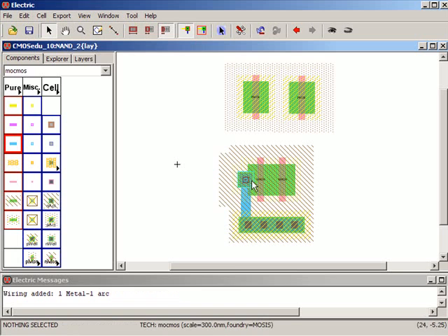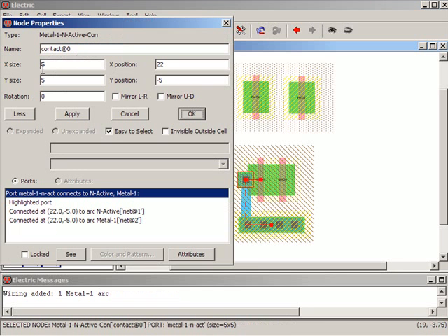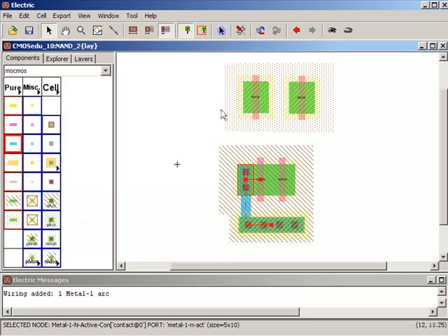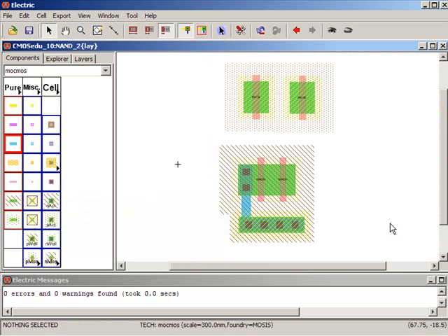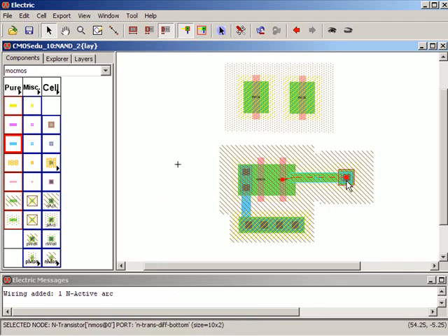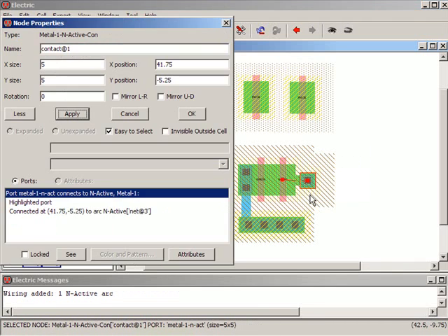I'm going to have to make this wider. Okay, so let's do a Control I, change the size of that in the Y direction to 10 roughly. Apply, close, zoom. Okay, looking good. Do an F5, no errors. Fit. Let's go up and make this a little wider so I can, actually before we do that, let's put another inactive contact here, and then right click, drag it over, pull this over, Control I, Y size 10, apply, move this up a little.